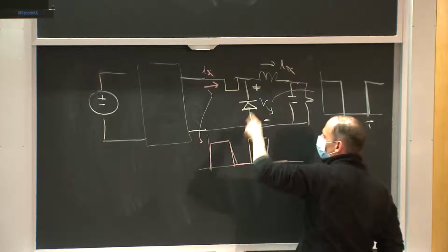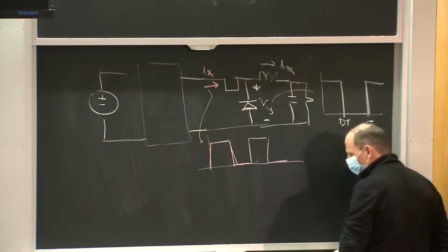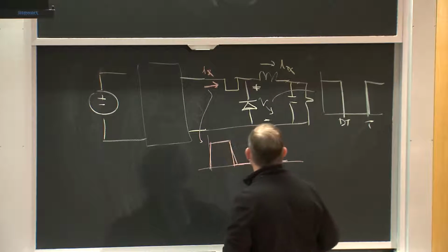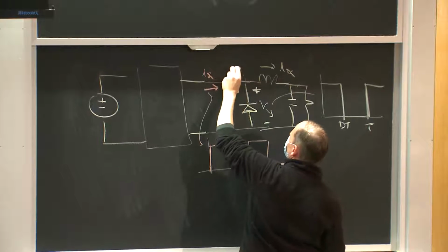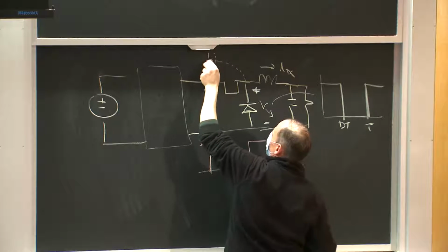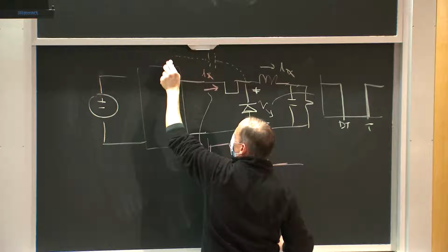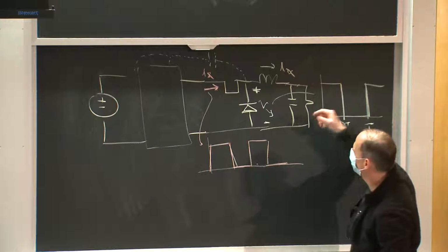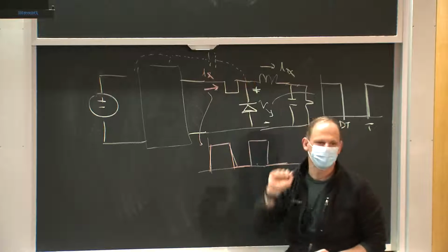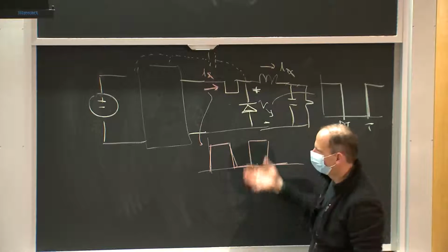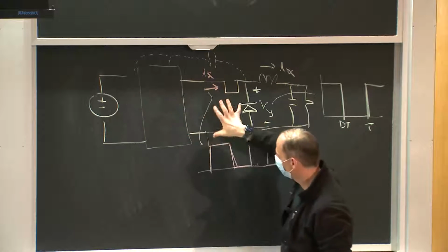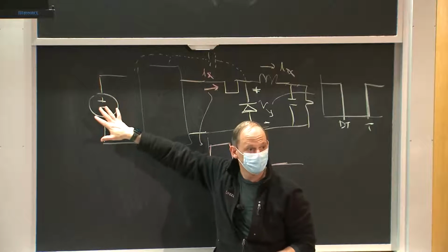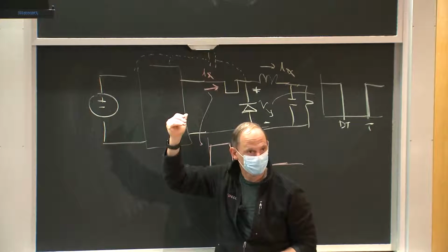Now that doesn't appear specifically out at the converter, but remember, I might have some parasitic capacitance coming back here and either into my filter somewhere or towards my input somewhere. So basically this very sharp voltage injects currents back. And that can appear as noise either within my circuit or at the input or output somewhere, okay?